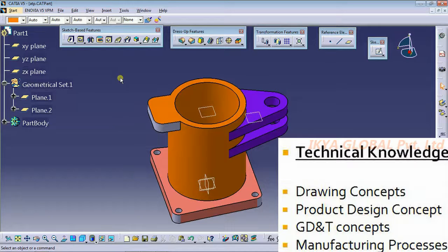Why? What happens if you increase the thickness? If the plastic part should withstand a load, then what will you do? What type of design characteristics do you prefer? Like ribs, we use ribs, gussets like that. Then what are their design considerations? How much thickness do you use for those ribs?